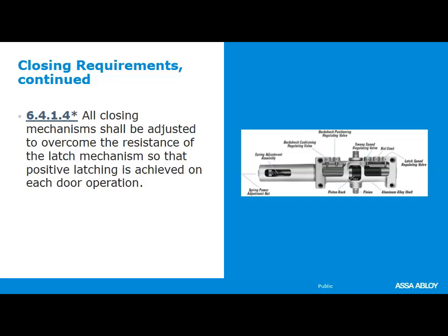So on all non-fire rated doors, interior doors, to meet ADA, 5 pounds maximum opening force. Fire doors take priority over ADA, and there is no minimum requirement for the 5 pounds of opening force like there would be for other interior doors. Adjusting the spring tension, the latch and closing speed is critical to ensure that the fire door closes and latches each time.